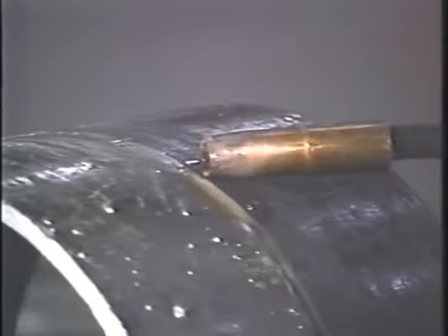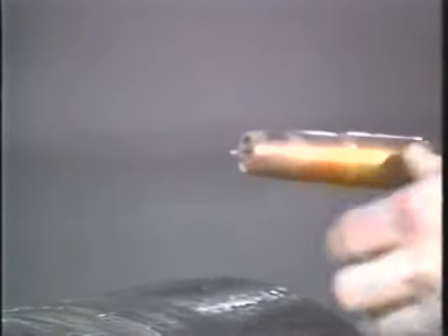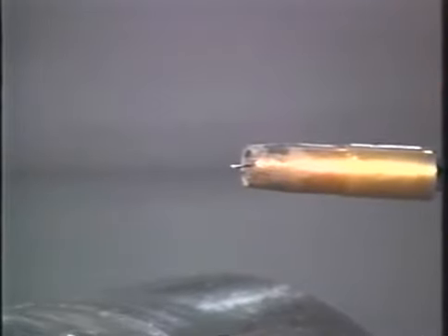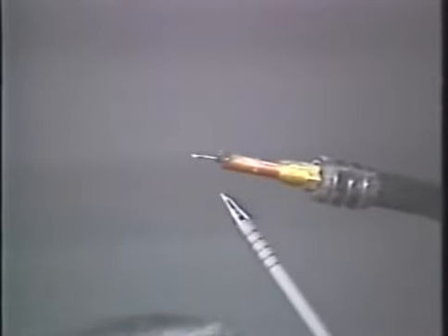If your wire stick-out, like many operators, is going to be a half an inch long, due to the fact that your contact tip is now down inside the nozzle, so we have a half to 5/8 of an inch, you will need at this particular setting an extra volt or two.